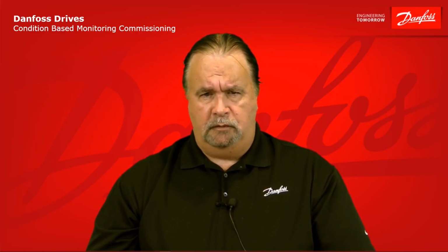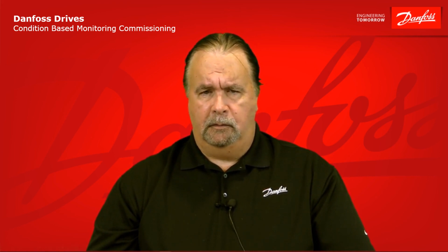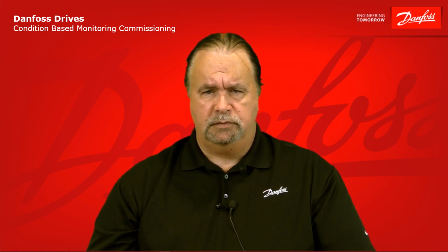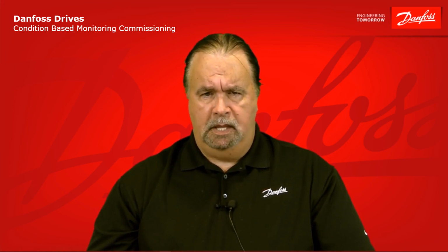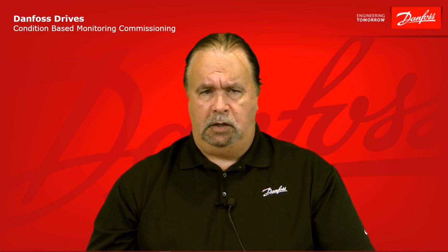CBM is a software feature called condition-based monitoring. It's an outstanding use of drive technology to implement predictive failure monitoring in the VLT brand of products designated FC102, FC202, and FC302. This can allow you to minimize or eliminate downtime and manage the maintenance of your equipment in a cost-effective and timely manner. This can remove, if not eliminate, most causes of emergency downtime.